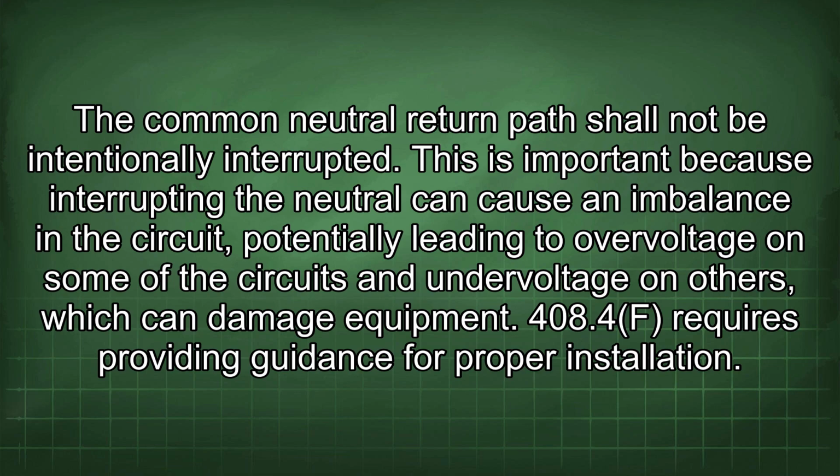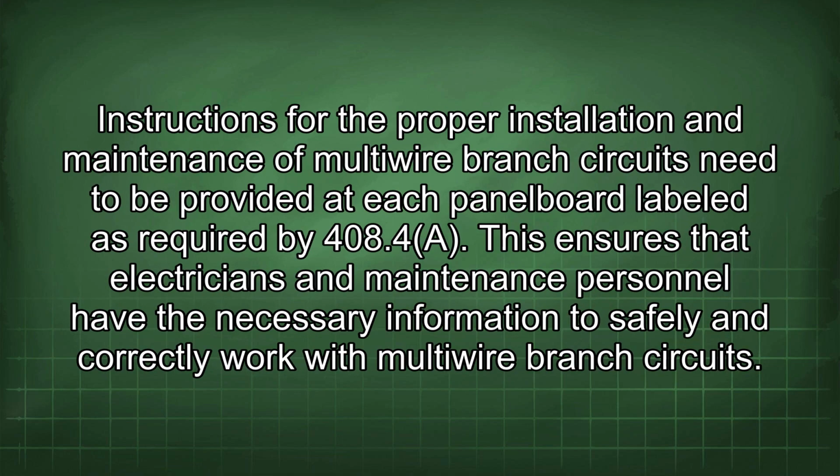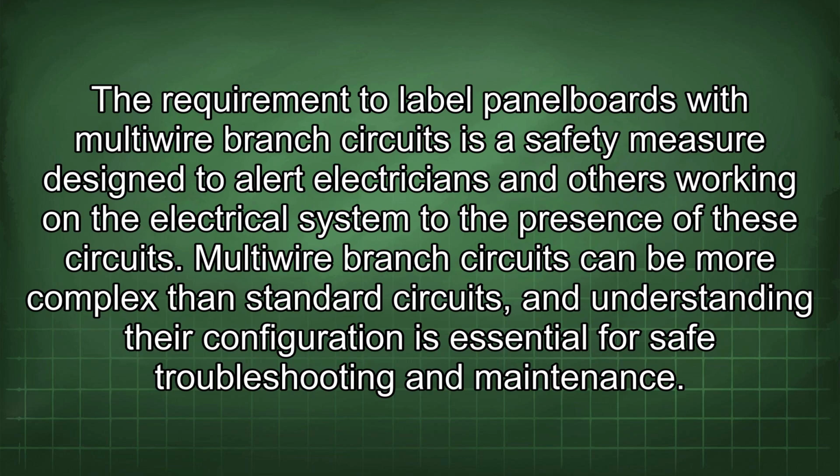408.4f requires providing guidance for proper installation. Instructions for the proper installation and maintenance of multi-wire branch circuits need to be provided at each panelboard labeled as required by 408.4a. This ensures that electricians and maintenance personnel have the necessary information to safely and correctly work with multi-wire branch circuits. The requirement to label panelboards with multi-wire branch circuits is a safety measure designed to alert electricians and others working on the electrical system to the presence of these circuits.